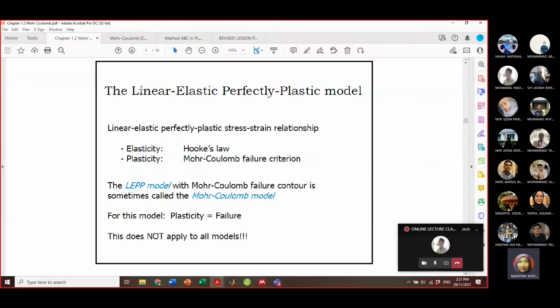I think the simplest thing is we want to use the Mohr-Coulomb, but then the Mohr-Coulomb is no longer linear. It becomes a linear elastic perfectly plastic model. It means that when you want to visualize, the thing that you may have at the end is something like this. You will have one part which represents the linear portion, that you can have as Hooke's elasticity material, and the other part is the plasticity zone or plasticity region.